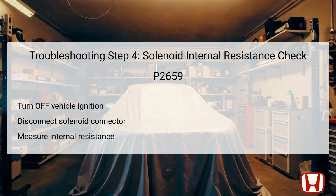Specifically, the resistance should be measured across the solenoid's terminals with the solenoid disconnected. At room temperature, a resistance reading between 14 and 30 ohms signifies that the solenoid is functioning correctly. If the resistance falls outside this acceptable range, it indicates a failure of the rocker arm oil control valve, necessitating its replacement. This step is critical as it confirms the integrity of the solenoid's internal wiring and coil.